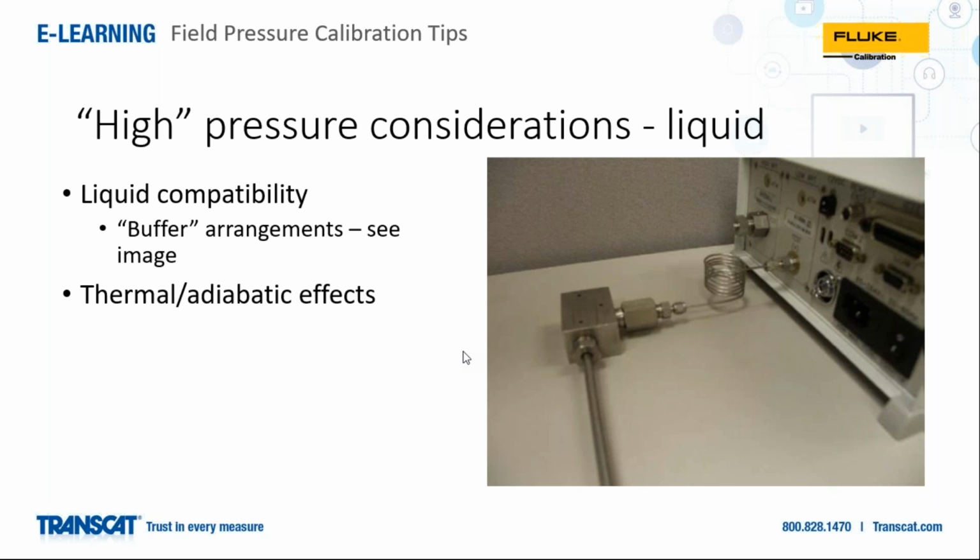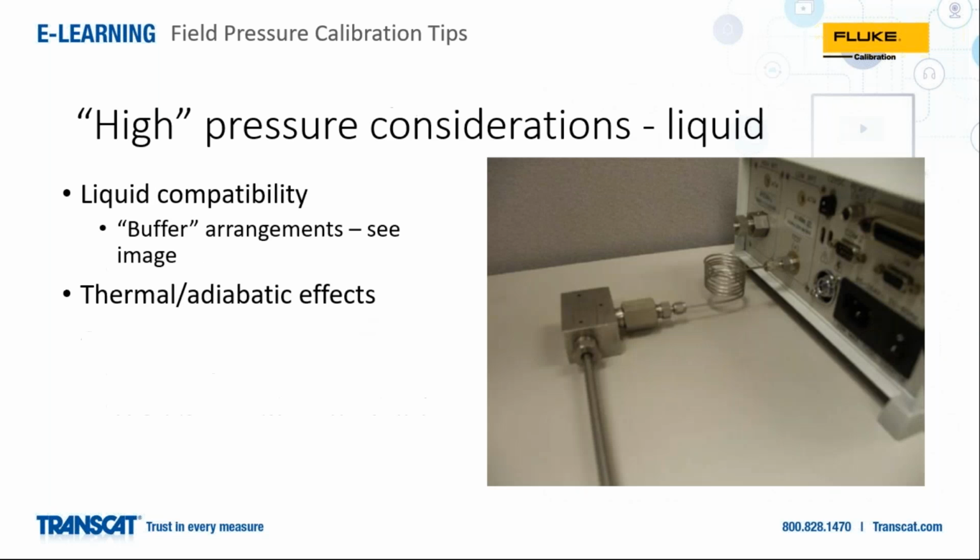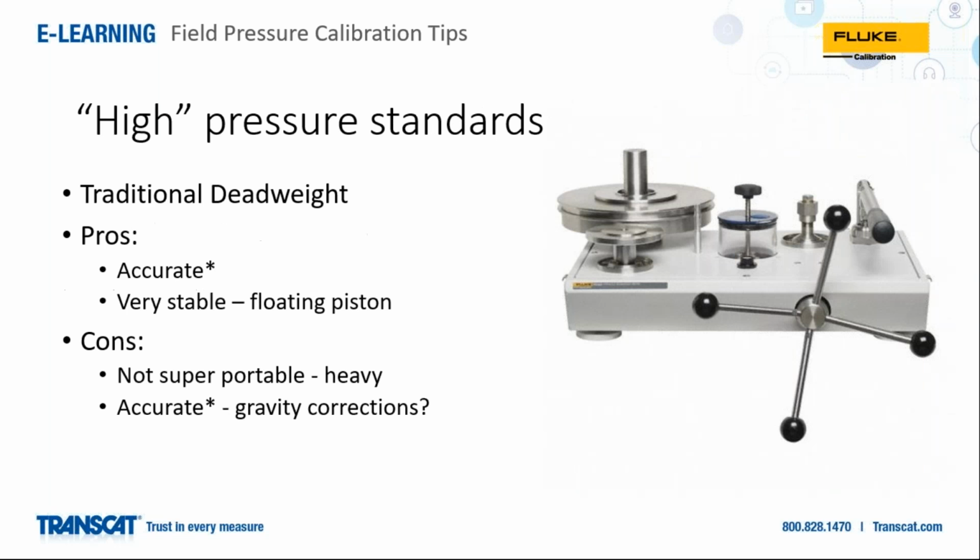Also, a consideration with high pressure liquid calibrations are thermal or adiabatic effects. As you generate pressure, you generate heat, which in turn generates more pressure. And this is evidenced as system instabilities. Some standards, as we'll see here on the next slide, can help compensate for this.